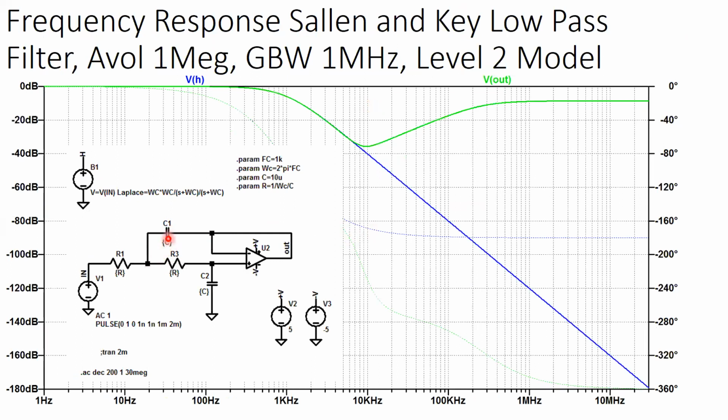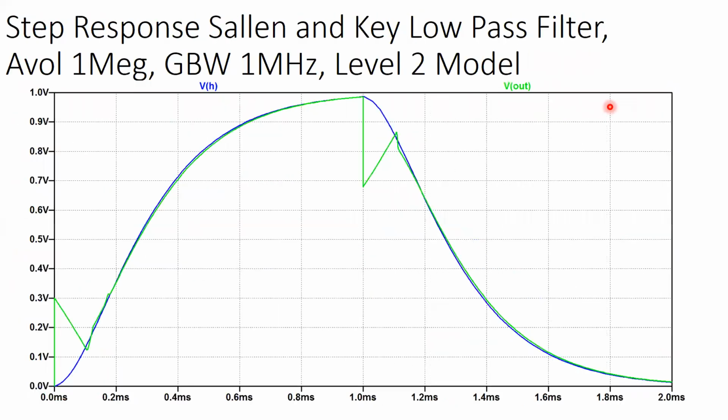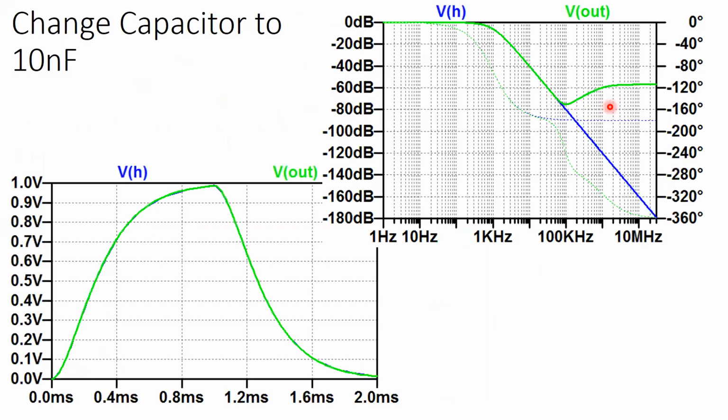I kept that relationship the same, but made this smaller, because when this op amp stops working, this just behaves like a high pass filter. So when the open loop gain is not effectively infinity, this is just garbage, which is why I make a big screaming deal about gain bandwidth in 110 and 110 lab.